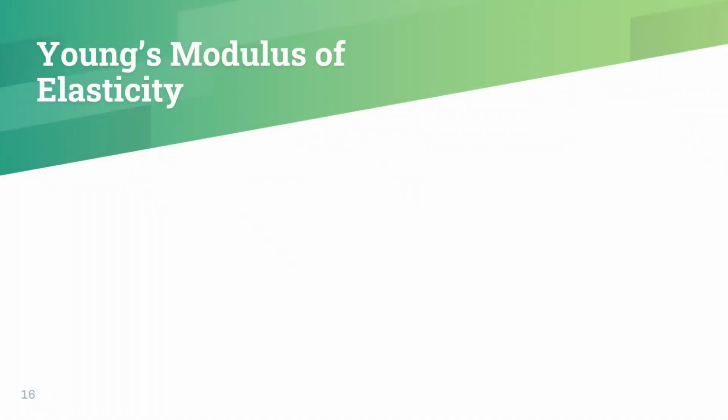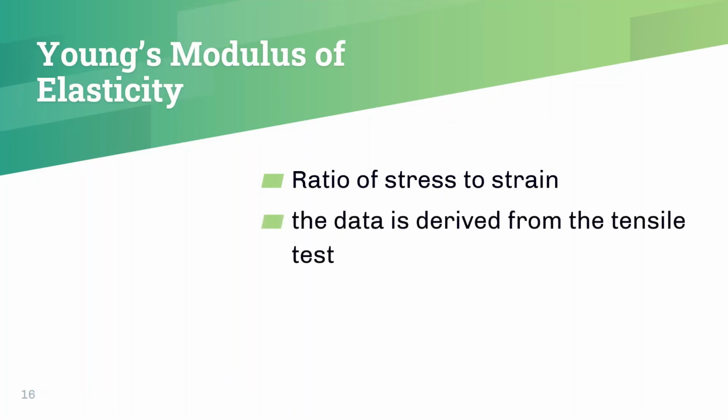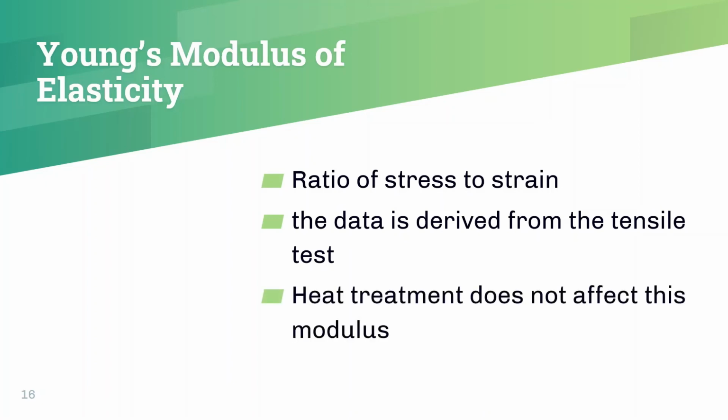Young's modulus of elasticity. Young's modulus of elasticity is the ratio of stress and strain. The data is derived from the tensile test. Malalaman natin ang modulus sa pamamagitan ng tensile testing na ginawa rin natin kanina or pinanood natin kanina. Heat treatment does not affect this modulus.